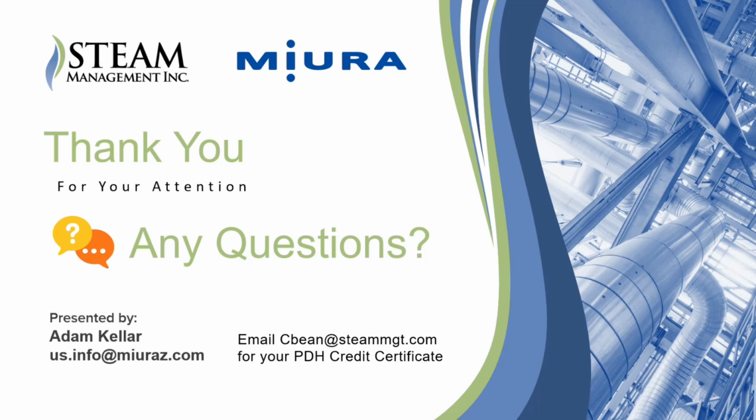But you do really have to keep an eye on your water quality and make sure you're doing your regular maintenance and keeping up with it. But you should be doing that on a fire tube too. Really, the stakes are higher in some ways because a failure of a fire tube boiler can be much worse, but the failure occurs much later. You see it in efficiency losses in a fire tube boiler, whereas in a Miura boiler, you might not see it until you get an alarm on the scale buildup, and then you have to clean the boiler. Or worse, you might have a failure if you ignore some alarms.